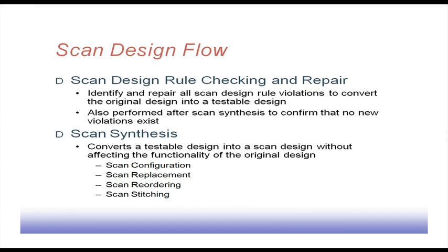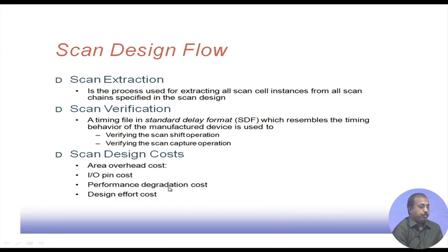Then the scan synthesis will convert the testable design into a scan design without affecting the functionality of the original design. So the flip flops will be converted to scan flip flops, the scan stitching and all that. These are the various stages in it: scan configuration, replacement, reordering and stitching.